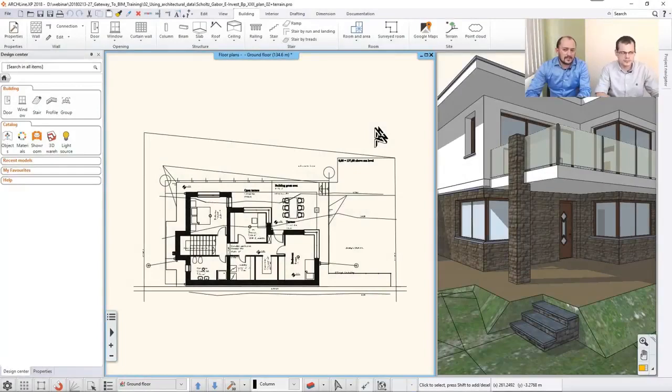There is one interesting thing that I should start with: even if you do not know where this file import command is, you can actually drag and drop any sort of file into ARCHLine, and this drag and drop import is by default supported, and all those file formats that ARCHLine supports will automatically be handled. So if you have a PDF file and you would like to process it in ARCHLine, just drag and drop it over the drawing surface and then ARCHLine will recognize it.